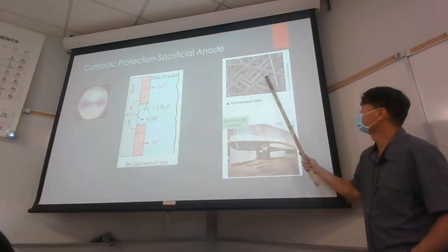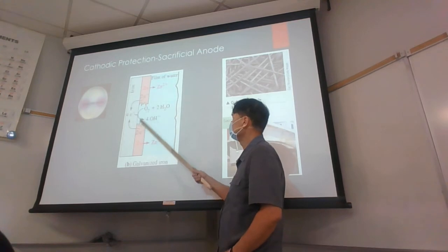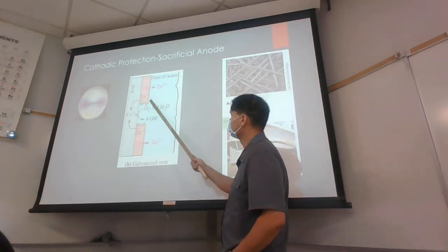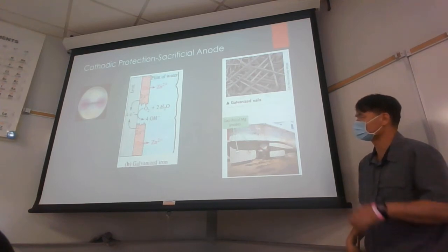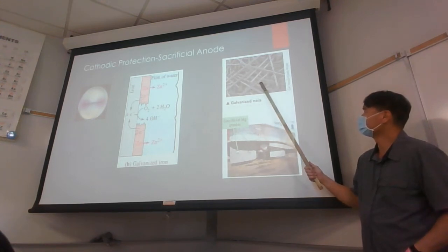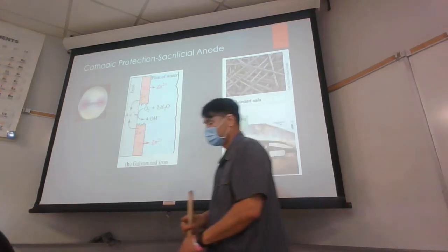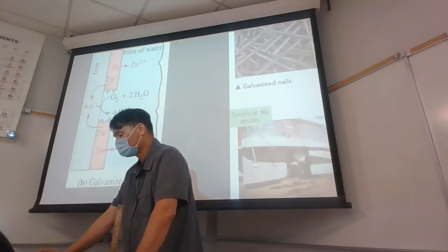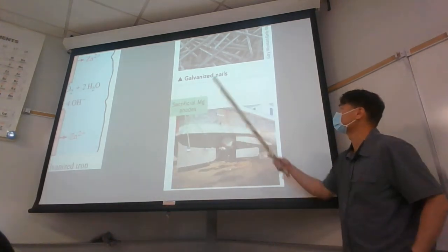Here's some galvanized nails here, some zinc-coated iron. Eventually, all the zinc is going to be oxidized, that is, it's all going to react. And then once that happens, the underlying iron can be attacked, and the iron will start to corrode. And so these are going to have some finite lifetime. Pretty soon all the zinc is going to be gone, and then the iron is going to start to corrode. And when that happens, it's going to lose its structural properties. We usually use those as building materials.